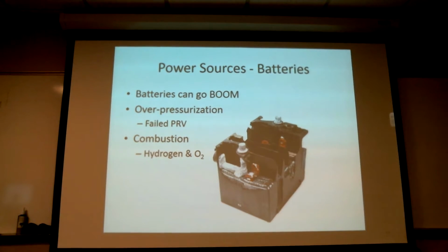So when you see a car burning on the side of the road, are the chances it's the battery that caused it? Well, the battery or a chafed wire. A chafed wire, dead shorted, that's very close to the battery, like the main battery lead over to the starter, and possibly some fumes. Now it's also possible a gas leak out on the hot exhaust. It's going to be one of those two things.